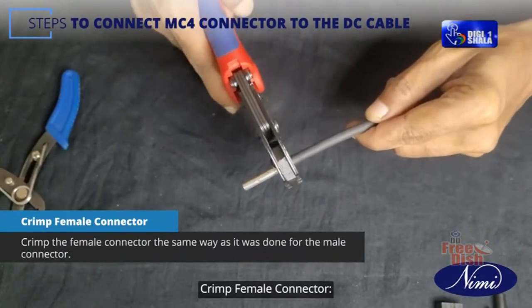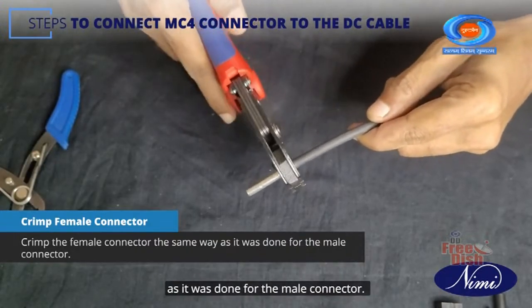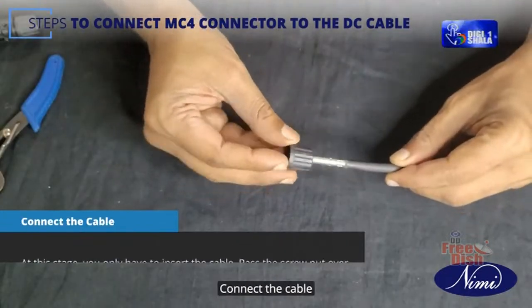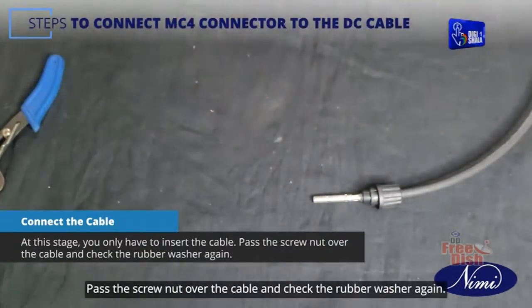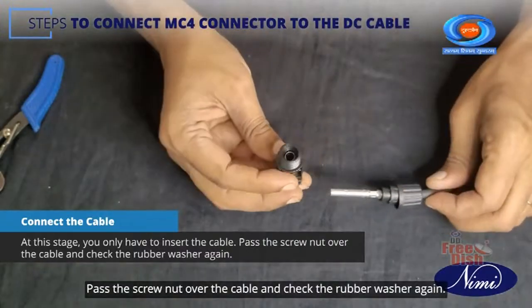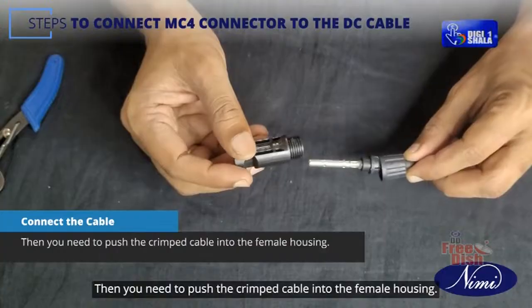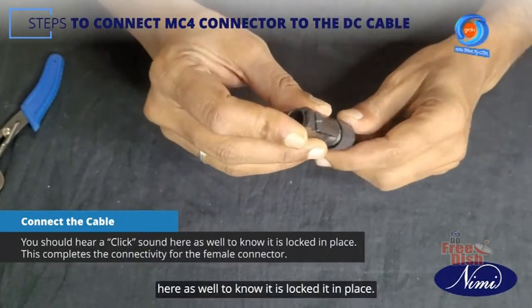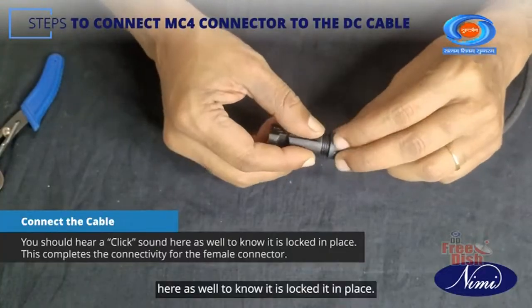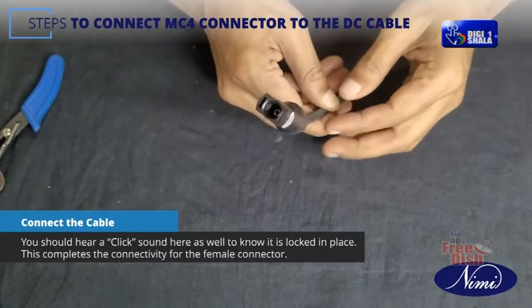Crimp female connector. Crimp the female connector the same way as it was done for the male connector. Connect the cable. At this stage, you only have to insert the cable. Pass the screw nut over the cable and check the rubber washer again. Then you need to push the crimped cable into the female housing. You should hear a click sound here as well to know it is locked in place. This completes the connectivity for the female connector.